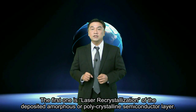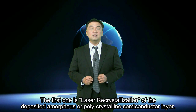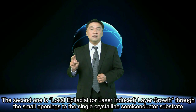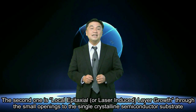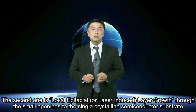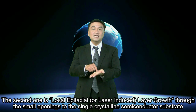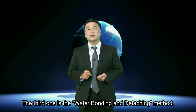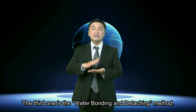The first one is laser recrystallization of the deposited amorphous or polycrystalline semiconductor layer. The second one is local epitaxial or laser-induced layer growth through the small openings to the single crystalline semiconductor substrate. The third one is the wafer bonding and detaching method.